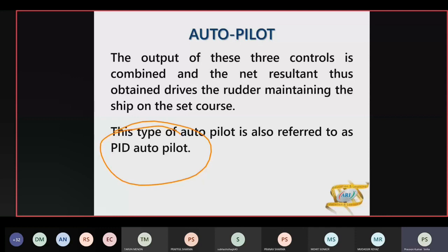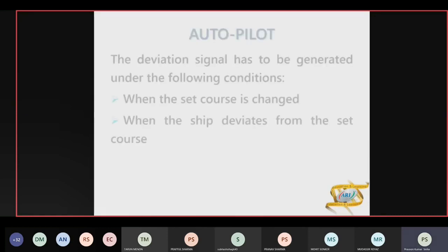The autopilot system will never go beyond that. आपने 20 degrees का डाल दिया, the autopilot system will never take the rudder more than 20 degrees port or starboard. So these are some of the controls that we have on the autopilot panel. These are user controls.